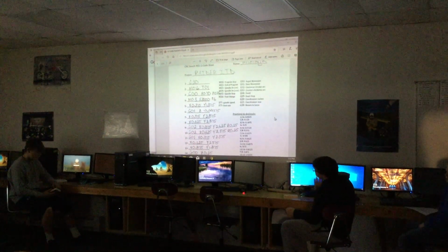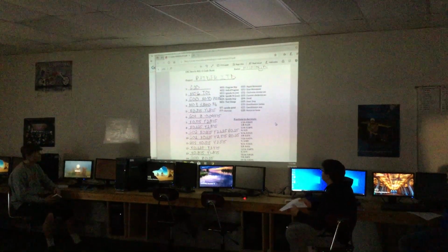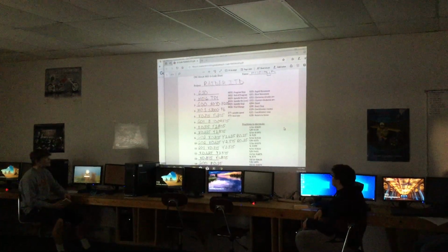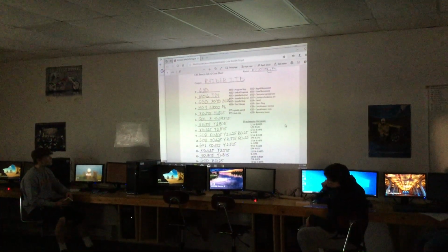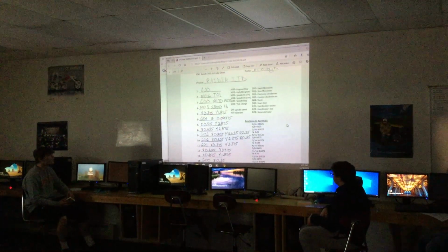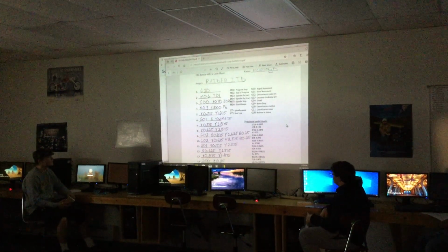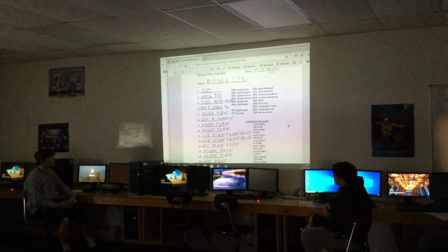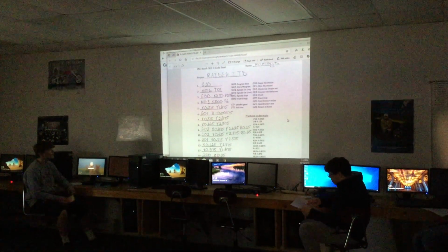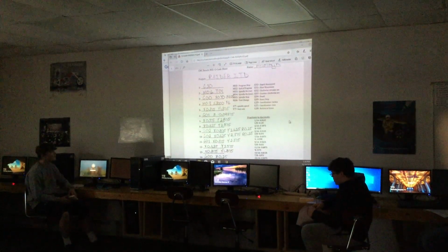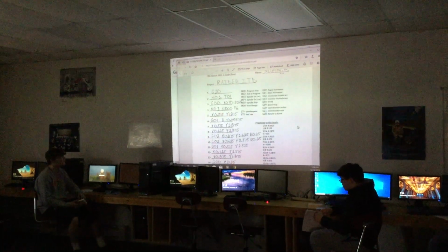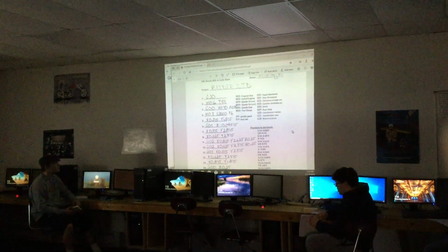Could be thickness, but that has more to do with F, which is called the feed rate, which is how fast the machine is going to move when it's cutting. The rapid movement increases production when you, for instance, lift the tool up and then move to a new spot. So it's kind of slow if you use just G01. It took me a while doing a couple programs on here to figure out I need to speed this up somehow. Well, then you have to enter G00 in and then go to the coordinates.